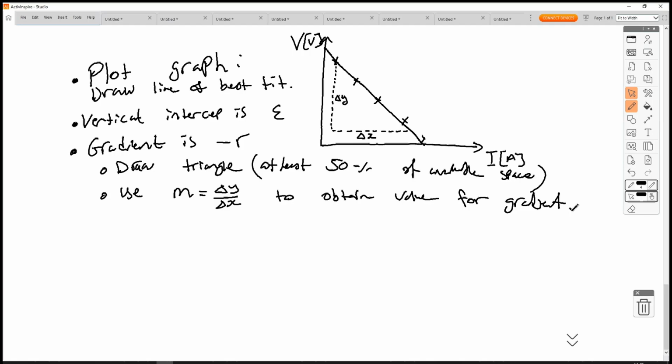Now if the resistor gets hot, again using 1.5 volts, we're not going to have a resistor that melts or catches fire. It's not going to get that hot. But the precaution that you take is that you switch off the circuit or open the switch, and I haven't drawn a switch in my diagram, but you open the switch when you're not taking data, when you're not taking any measurements. Because the resistor could heat up, and if the resistor heats up, that could change its resistivity. Because conductors will increase their resistance when their temperature is high. So you want to prevent that from happening.